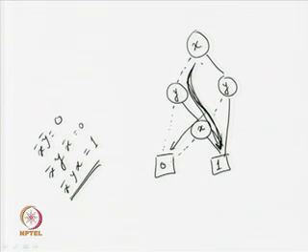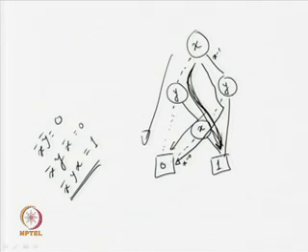Similarly, we are going to get another inconsistent part, x equal to 1, y equal to 0 and x equal to 0. So, here x equal to 1 and x equal to 0, this is also inconsistent. So, we cannot have any valuation through this particular part. Okay. So, this is the problem that we are having. So, if we look into the basic definition of BDD, then valuation of this particular Boolean function has to be done over consistent parts only. So, this is a consistent part, we do not have any problem. x equal to 0, y equal to 0, we are going to get this particular value. Okay. Similarly, this is also another consistent part, x equal to 1, y equal to 1, we do not have any problem. So, valuation has to be defined over consistent parts, as we may have inconsistency.